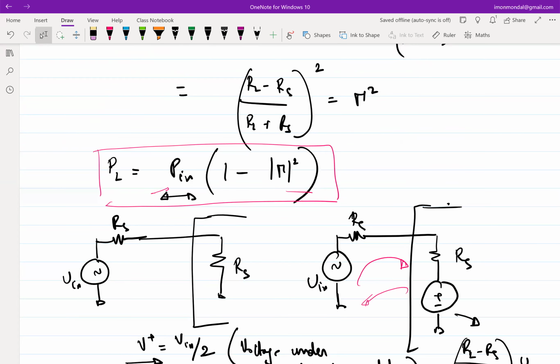Or rather, not from the circuit, but from the source. But the maximum power I can draw, the condition is under matched. Otherwise, I'll not be able to draw, right? So if I have to think about voltage going in and voltage getting reflected, then I have to distinguish under what condition the maximum power gets transferred, and then use the actual reflection coefficient to find out what is the reflected wave.